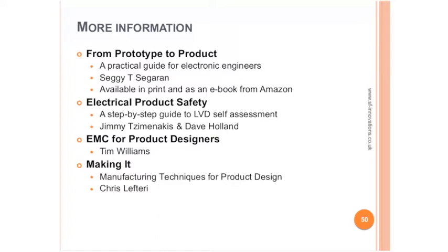Okay. They tend to be residential versus industrial applications. So if you have a product that is targeted to the residential market, the EMC standards for that are different to industrial applications. I wouldn't advise getting a spectrum analyzer unless you have some good experience in RF testing. If you do, then certainly a spectrum analyzer would help. But coupled with the spectrum analyzer, you need the right type of antennas as well.